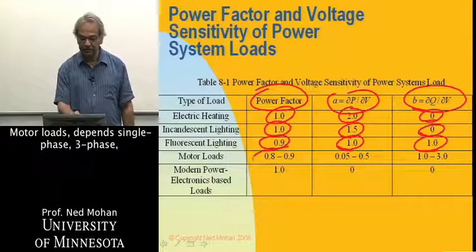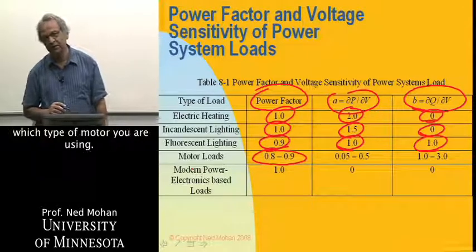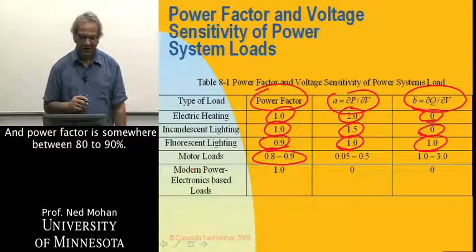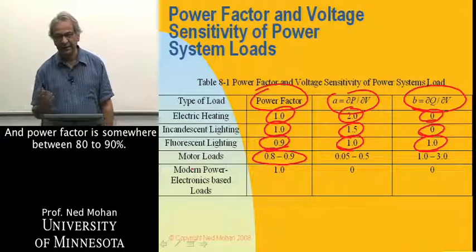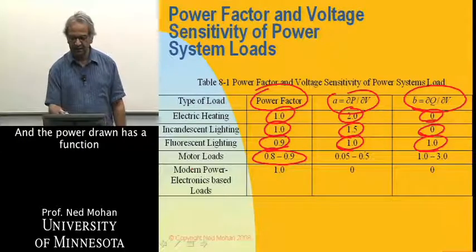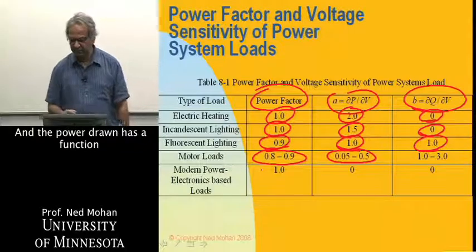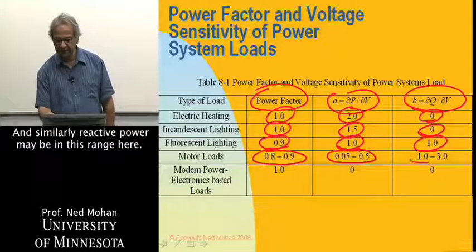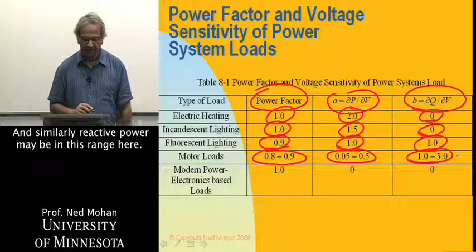Motor loads depend on single phase, 3-phase, which type of motor you're using, and power factor is somewhere between 80 to 90%, and the power drawn as a function of voltage is in this range, and similarly the reactive power may be in this range here.